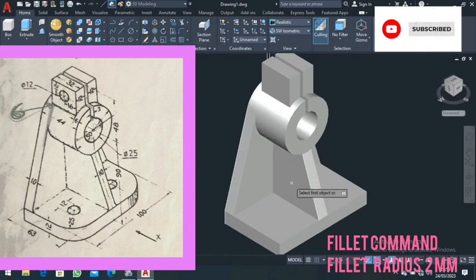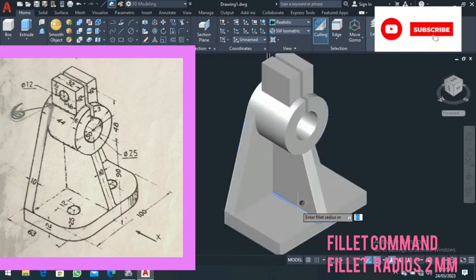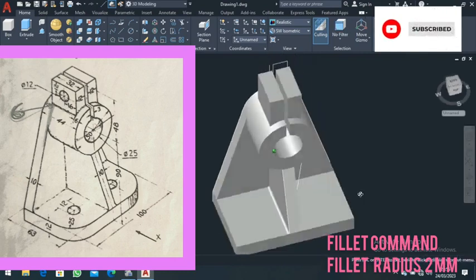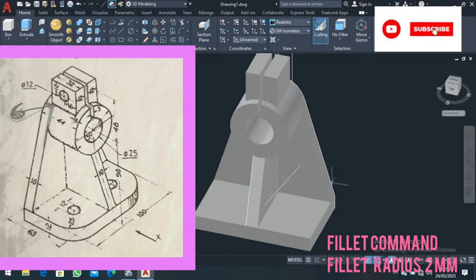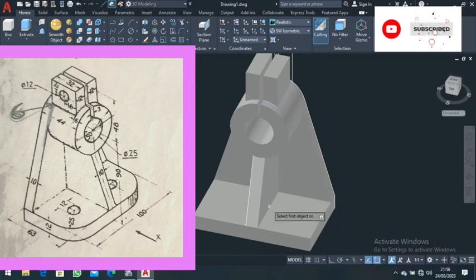So you choose your fillet, you specify this point, then you fillet it through a distance of 2, you enter in 2, then you can rotate and you also fillet this other side. Before filleting, you can remove this line, so you delete that line, then you come to fillet, you choose this part, then you enter in the fillet radius, which is 2.